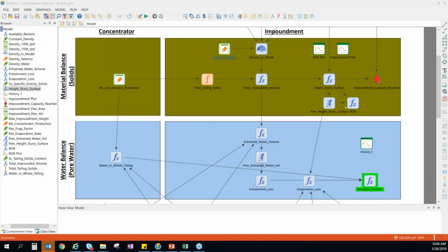And if we have a maximum pond volume, and we assume that it's going to be maintained, then we can look at our beach slope, we can look at the geometry of the foundation, we can use a three-dimensional CAD model and come up with a relatively reasonable area for our pond, okay? Wet versus dry beach, that's a little more challenging.